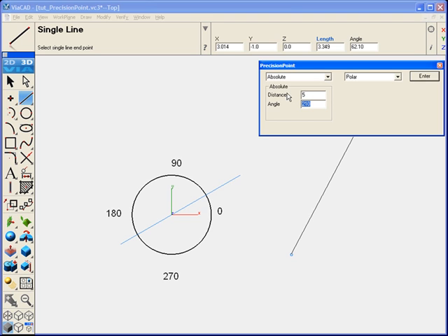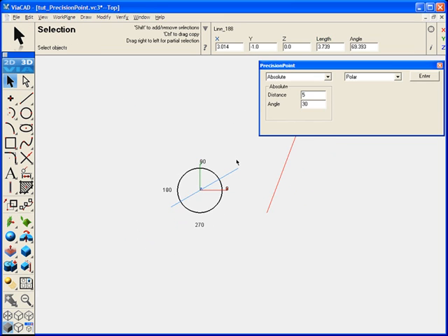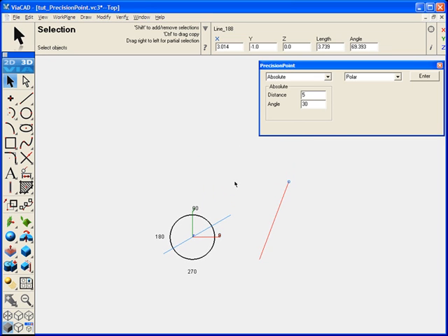Now we can move our start point off of 0, 0, start our line, and then draw a line that's, say, 5 inches long and at a 30-degree angle. Remember, the angle is an absolute angle. It's the angle of the drawing origin to the point in absolute polar mode. So it's 30 degrees from the origin to that point we just drew to.